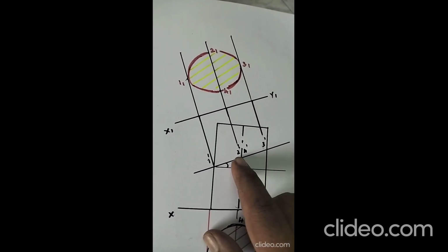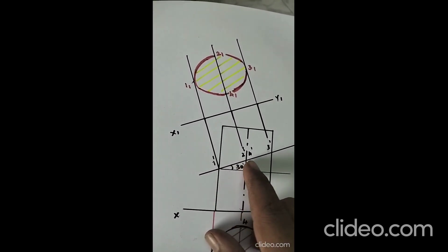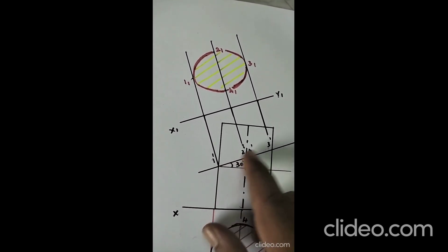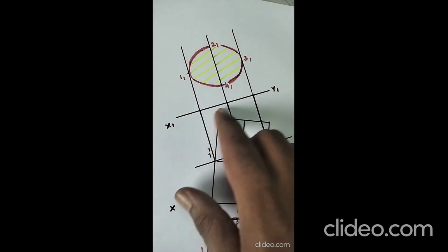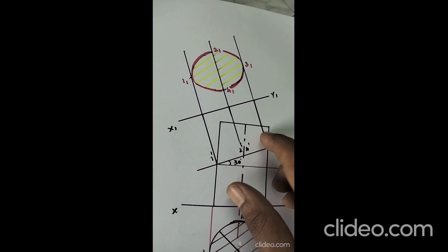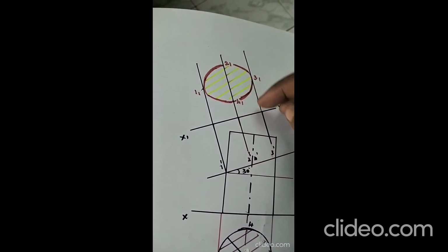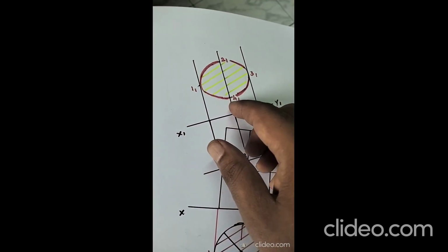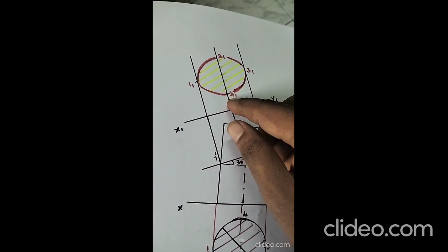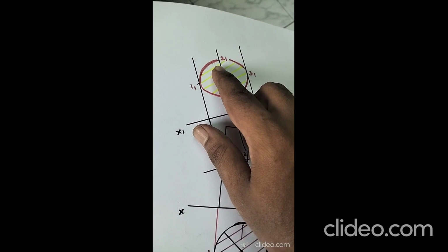Then the second step is to draw all the numbered corners, that is the cutting points 1 dash, 2 dash, 3 dash and 4 dash. From all these points we have to develop perpendiculars to this auxiliary reference line. That is 3 perpendicular lines we are getting, and extend the lines beyond the auxiliary reference plane like this. Now we have to mark the answer using the number notation in a different way: 1 suffix 1, 2 suffix 1, 3 suffix 1 and finally 4 suffix 1.